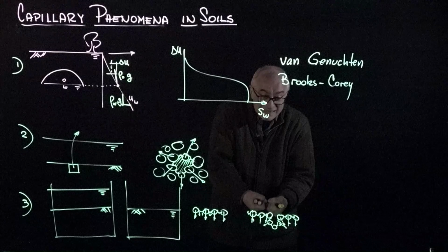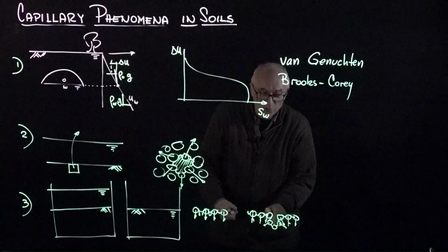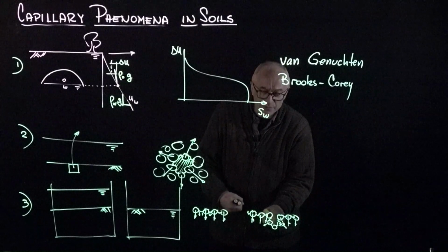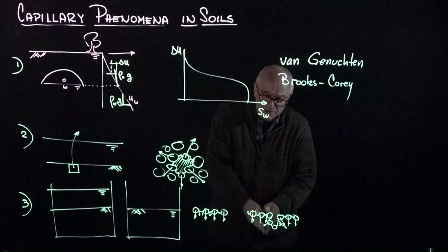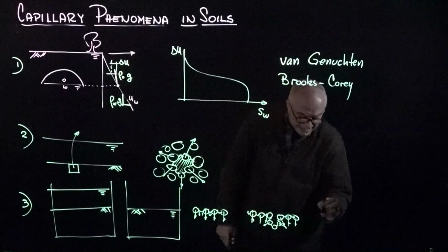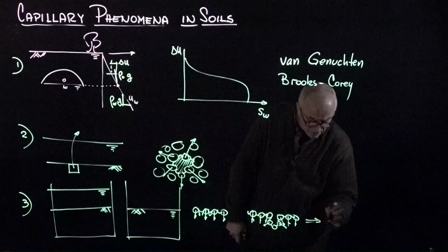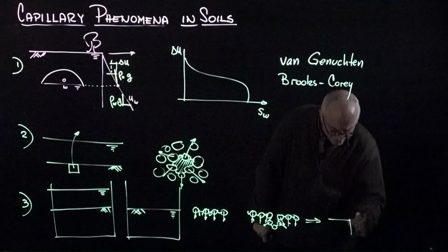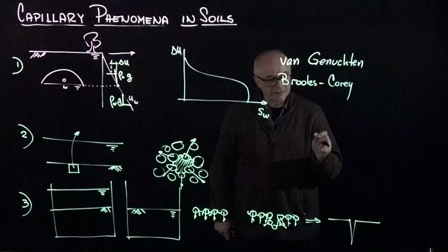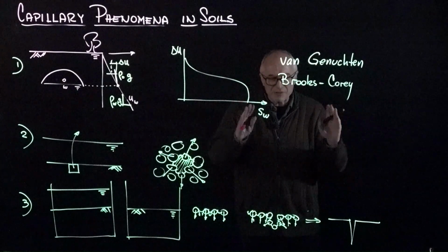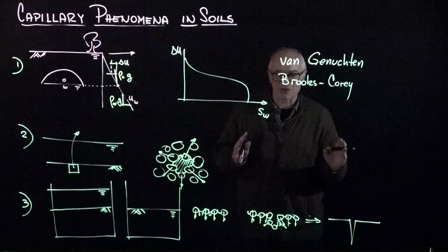And this lateral pull-out is going to enlarge the pores, and because the pore gets enlarged, the meniscus invades even further and further, and that leads to what we call a desiccation crack. I insist, I am assuming absolutely no tensile strength in this material.